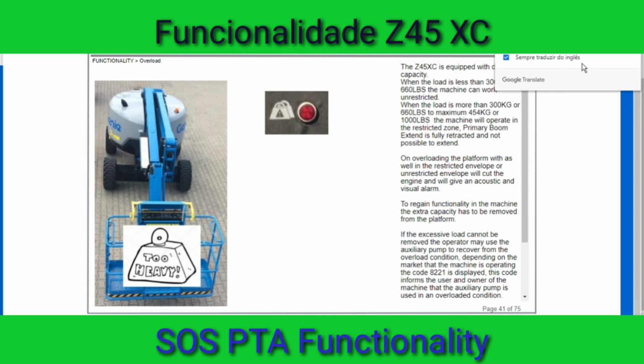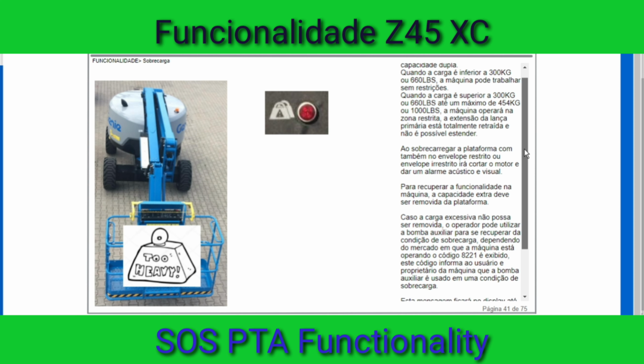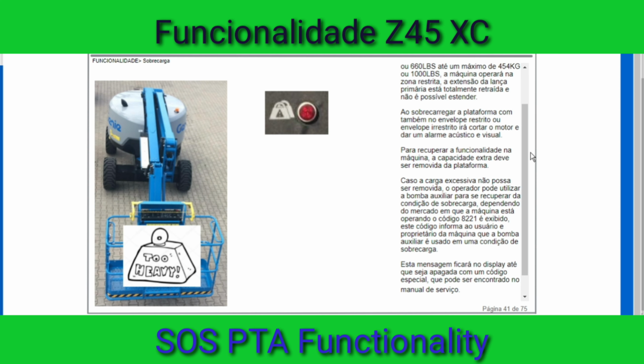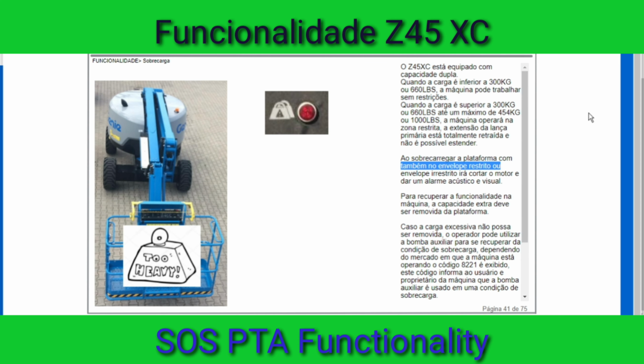The Z45 XC is equipped with dual capacity. When the load is less than 300 kilos or 660 pounds, the machine can work unrestricted. When the load is more than 300 kilos or 660 pounds to maximum 454 kilos or 1000 pounds, the machine will operate in the restricted zone. Primary boom extend is fully retracted and not possible to extend.